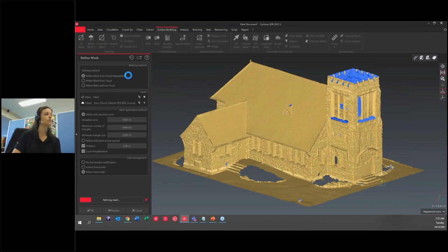Then when you have a cloud, most of the time, what we're doing here is the best way to go, just 2 steps in cloud interpolation. What the interpolation means is that instead of simply adding the real points of the cloud into the mesh at this stage to add the details, it's actually going to look in a smarter way at the cloud. And within the cloud thickness, it will compute which point is actually the best to use, looking at the local noise. So the idea is that you will bring in points that make sense compared to the mesh we already have.